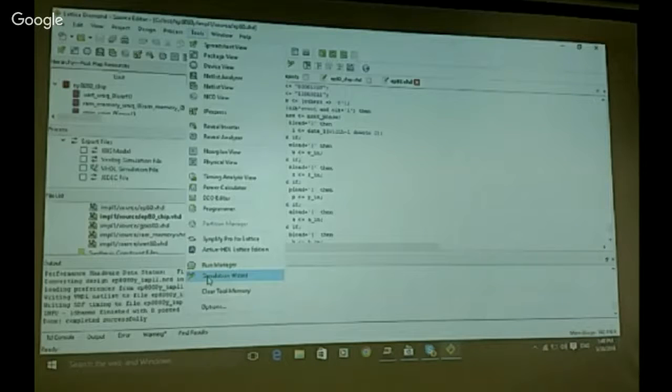Actually, if you follow the instruction from a VHDL textbook, they don't recommend you do it this way in one file. It actually asks you to break down everything into small chunks: each register in one place, all the multiplexers in another place. But I found out everything just fits in one file.